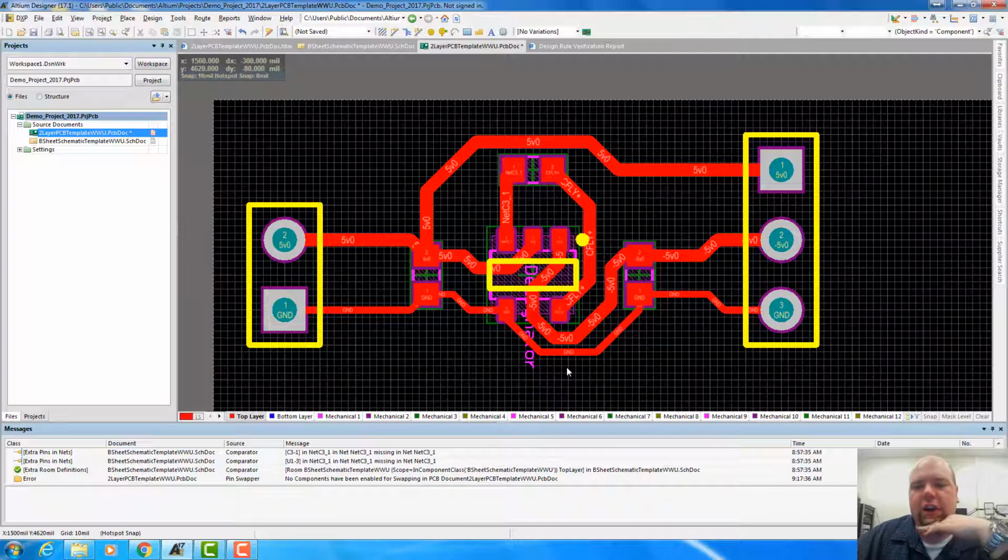That's a sheet of copper. Anywhere you can use copper, you make that copper connected to your ground signal, and that minimizes the resistance along the ground signal. It prevents voltage drops across your ground signal, which minimizes noise and keeps this reference constant across your board. So we're going to place a plane. We're going to do a ground plane really quickly.